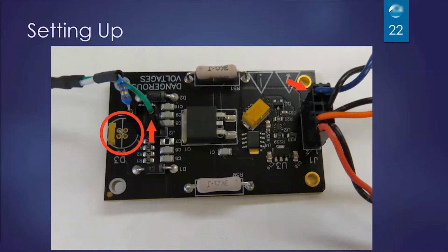Next, there's an arrow on the optional current monitor cable. You see the red arrow is pointing to the green wire. That's towards the center of the printed circuit board. There's a resistor that's towards the edge of the printed circuit board. And finally, there's a short on the laser diode. We test with shorts here in the factory. If you have your laser diode available, you can solder your laser directly to it at this time.